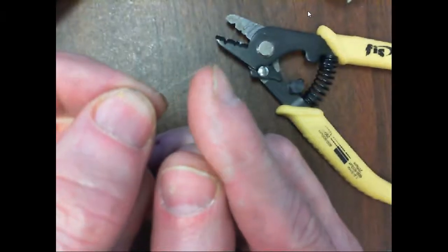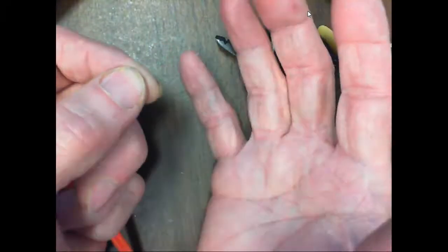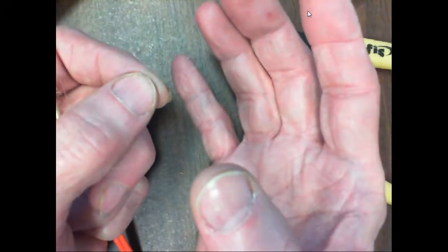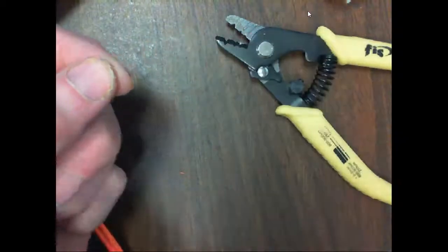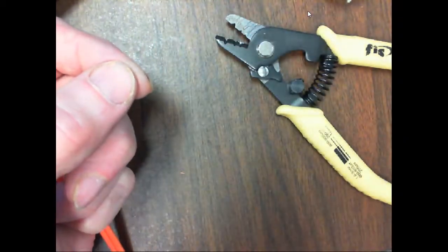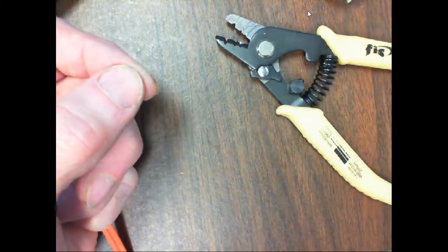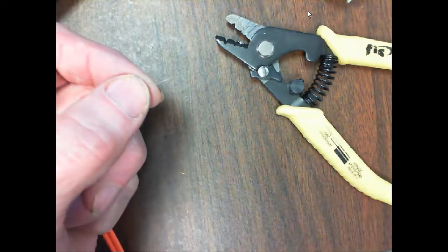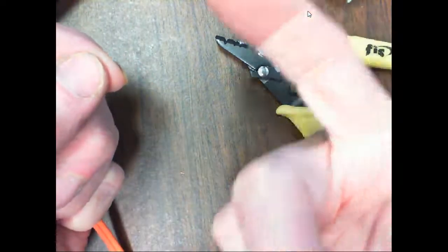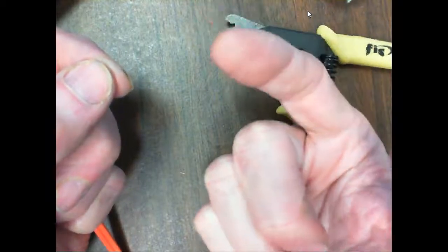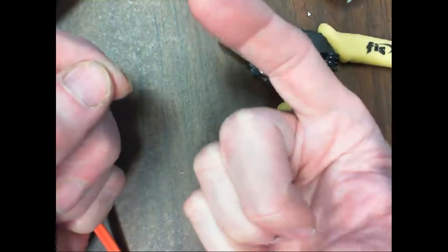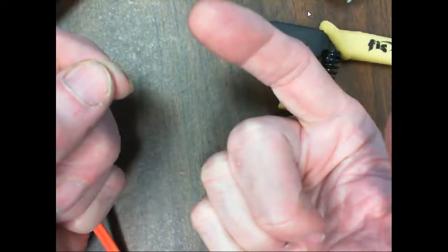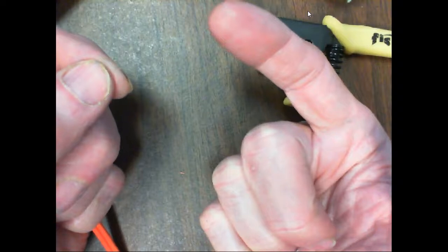And then this right here, you're looking at the cladding, and you can't see the core. The core is inside the cladding. Now, what's so nice is the cladding gives us two functions. It's what's causing the light to reflect back in the core, but it also gives us the ability to set a standard size. So this is 62.5, so that means the core is 62.5 nanometers. And the cladding is 125 nanometers.